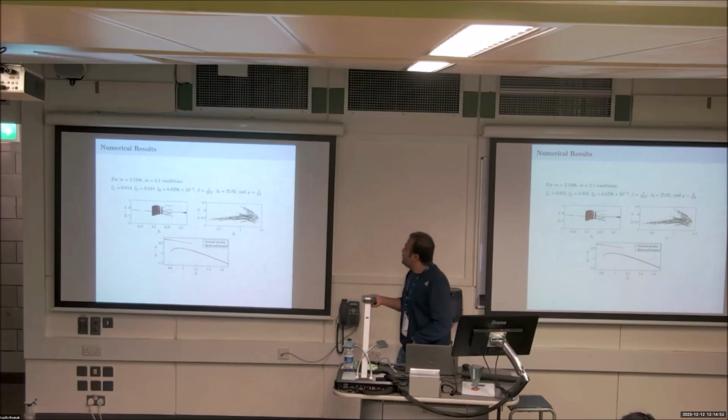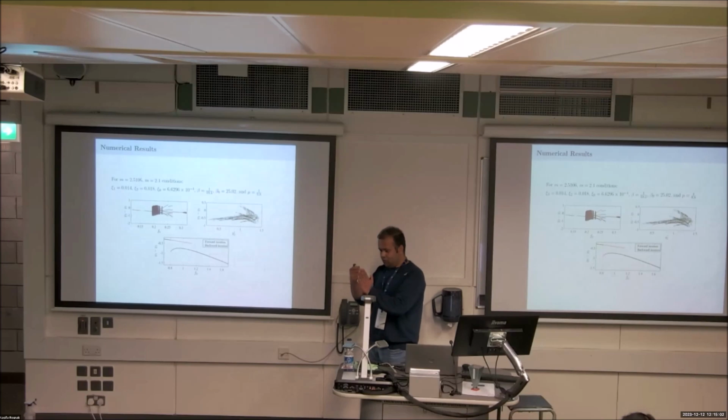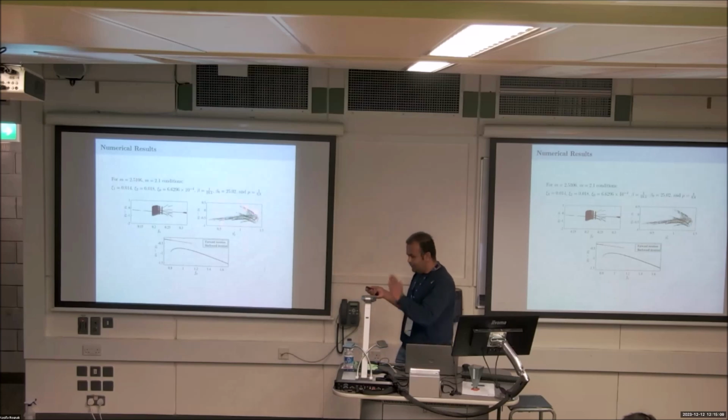And not only that, this chaotic region, like in the 1 degree of freedom system as well, has a finger structure, but it is a kind of fuzzy behavior because the impacting wall, which is added to the mass, is also moving. So both are moving, and that's why this fuzzy behavior is coming. If we stop one mass, this will be a prominent finger structure. And when the mass m value is close to an integer value, we are getting this kind of behavior.